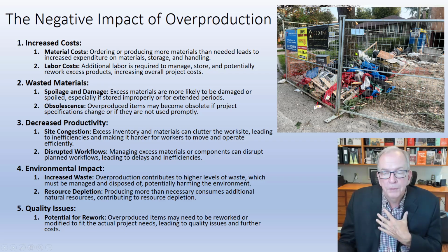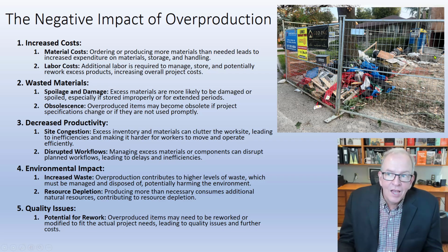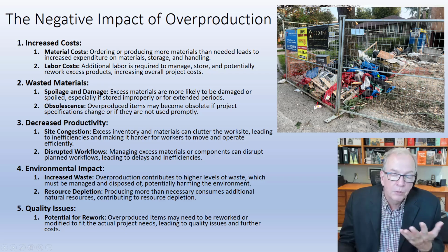In our particular city, and around the world, I know I have viewers from pretty much every country, we have this tree protection zone. So this is supposed to be guarded around the drip zone, and there's not supposed to be things stored or laid there. But because this site has a lot of things haphazard all over the place and extra materials and different things going on, they have no place to put it, and they're not keeping a very clean site, so they're not taking it away either. And so they're completely encroaching on the drip zone, the tree protection zone for this mature tree here.